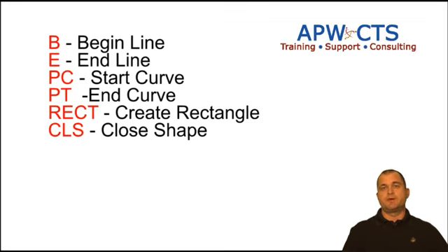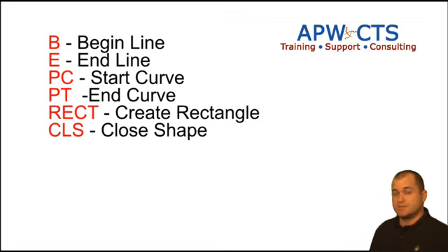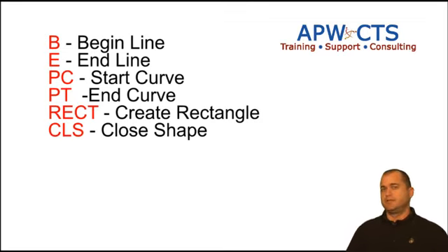Now there's a bunch of other options as well that you can use, but these are kind of the basics that really get you started using the figure codes and the line codes to collect data out in the field. So just make sure that whatever you use out in the field, you key it in properly with the right spaces and the right nomenclature, and then it is tied into your line code set that's inside of Civil 3D. And when you process it, you'll get a very successful field to finish project.